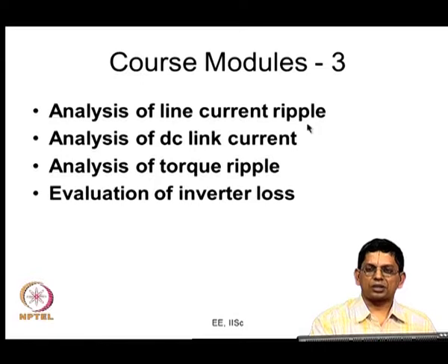The harmonics cause harmonic currents and therefore a current ripple. The harmonics also cause harmonic fluxes, and the fundamental flux and harmonic current, and again the fundamental current and harmonic flux, interact to produce pulsating torque. So, we discussed this pulsating torque for the low switching frequency case and also for the high switching frequency case. For the low switching frequency case, we tried to evaluate the 5th, 7th harmonic voltages, etc.